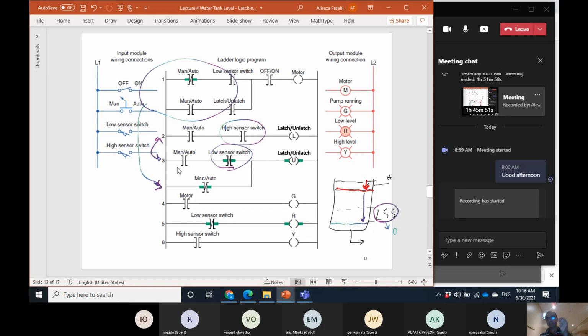I just want to be sure that the delay could be in the order of milliseconds, 100 milliseconds, 10 milliseconds, or something like that, if there is any. Let's assume that it latches at the end. Yes, there would be a delay in the order of 100 milliseconds, but that is the scan time, or the sample time. Generally in PLC programs, it is in the order of 100 milliseconds. That is not that important for this one. It's not important whether we move this rung number 1 to after or before that.